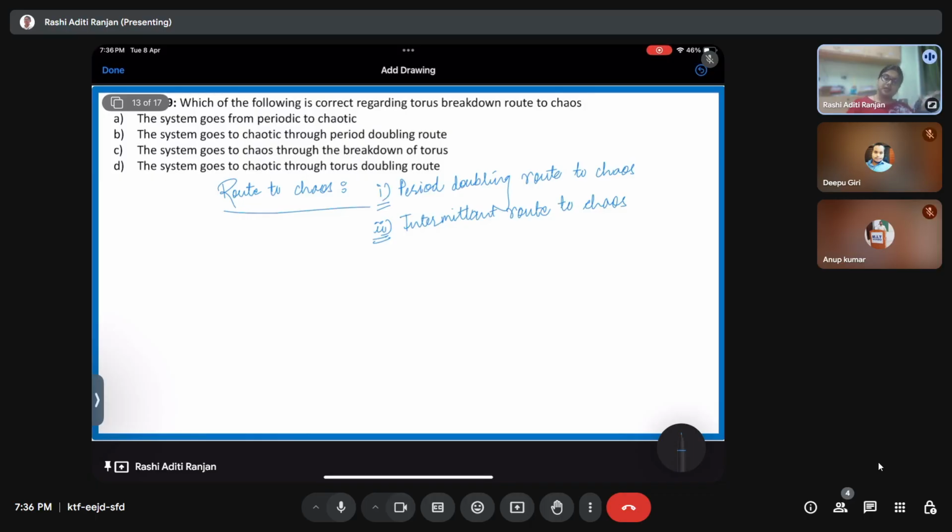Further increase of the parameter showed that with the increase of the patches, their time period and occurrence, there was a time that most of the response was chaotic and there were small patches of periodic response. Further increase of the parameter led to the whole chaos response. The periodic response completely vanished from my time response, right? So that was the intermittent route to chaos.